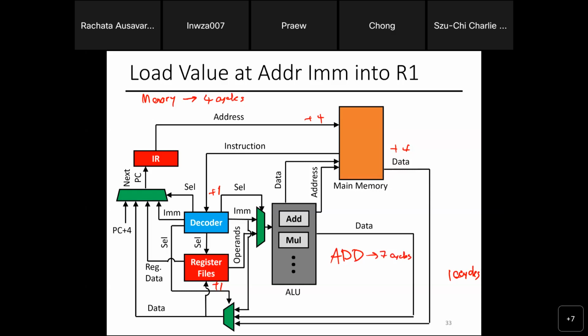So with a multi-cycle processor, one thing you can see clearly is now add is faster than a load, right? Now let's assume a multiply takes 5 cycles, add takes 1 cycle. In this case, multiply will be 11 cycles, right? So you can see now each operation will take a different amount of time, and I can clock a lot faster this way, all right? So that's the benefit of multi-cycle architecture.